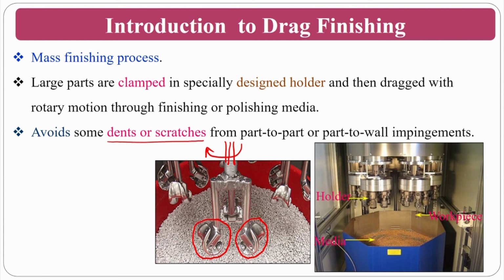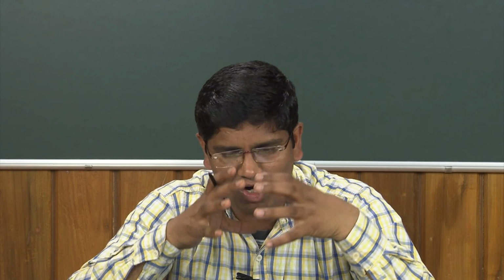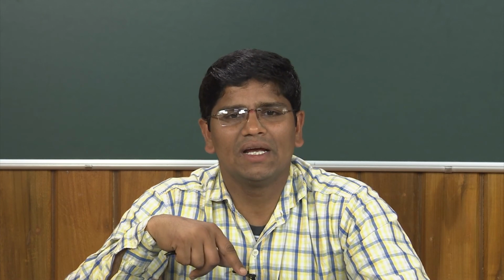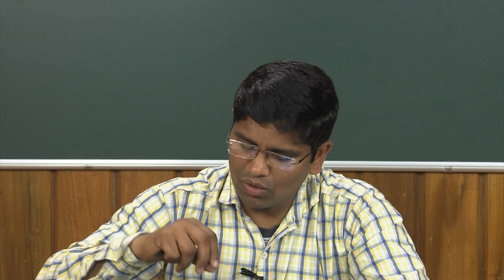The beauty about this particular process compared to the previous process is, in the previous process you are just putting all, assume that I am putting knee implants in it, then I am rotating with respect to certain speed. What will happen? There is a chance of knee implant to knee implant contact also, but this will not be there in that particular operation, because these are fixed to a certain portion of this rotating part, and abrasive particles will have their own finishing action.